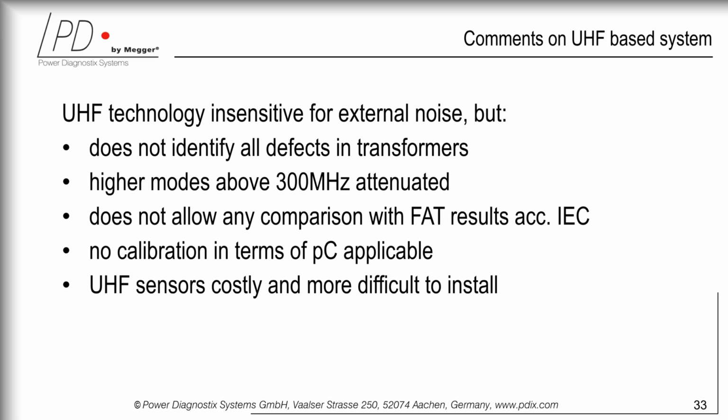There is no calibration available in terms of picocoulomb, as is the case with pure PD. And honestly, UHF sensors can be costly, and especially the oil valve, for instance, can be difficult to install. But this, in conjunction with, let's say, the bushing adapters and the acoustic, provides a very good image of what's happening within the transformer.